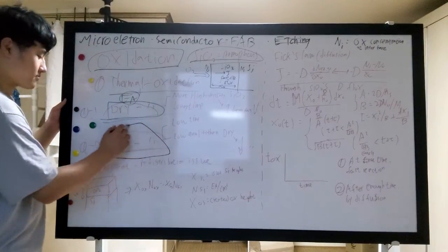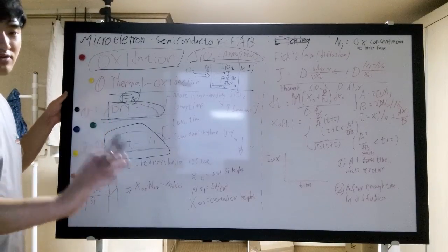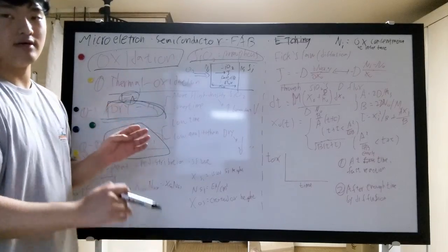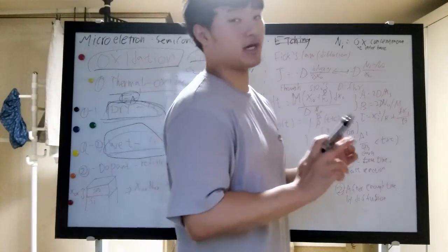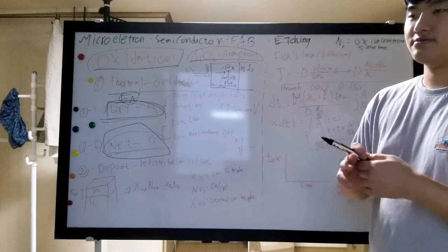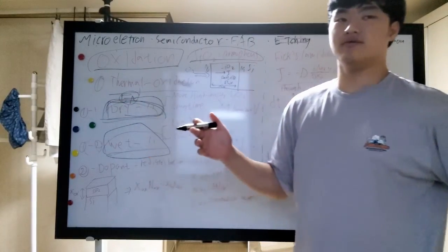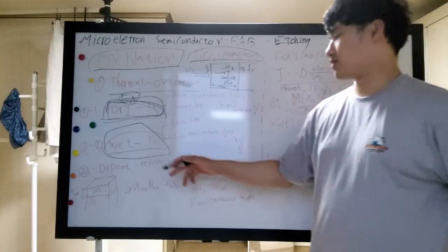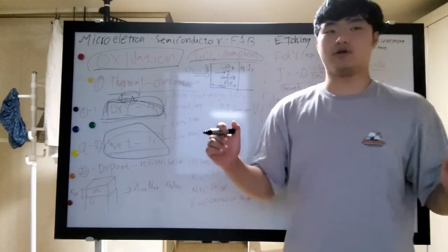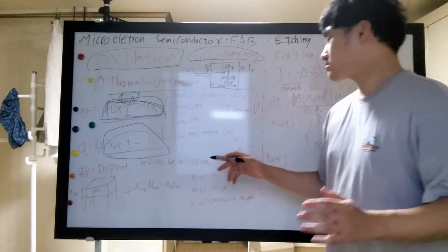For the wet process, the breakdown voltage will be somewhat lower than the dry process, but it has the benefit of saving time and being cheap. Just think like this: the dry process gives hardened and reliable silicon dioxide, and the wet process is cheap but can be commonly used for making products in a short time.